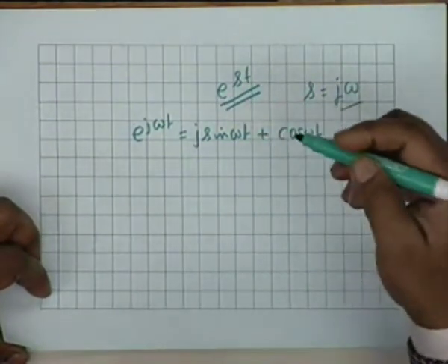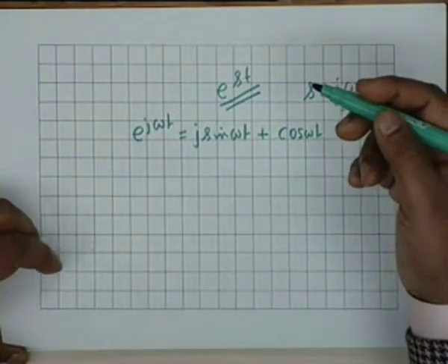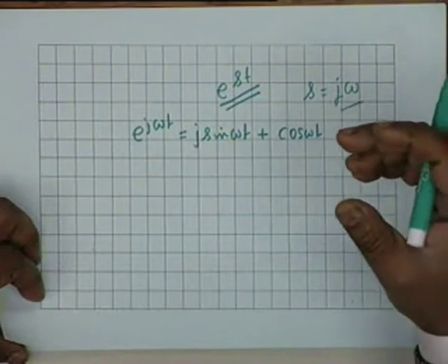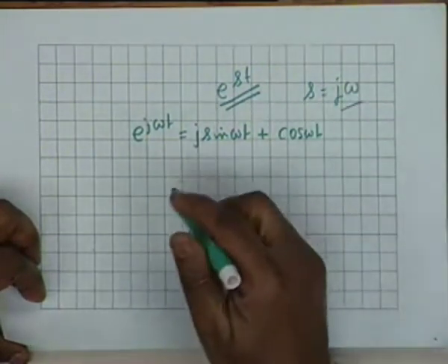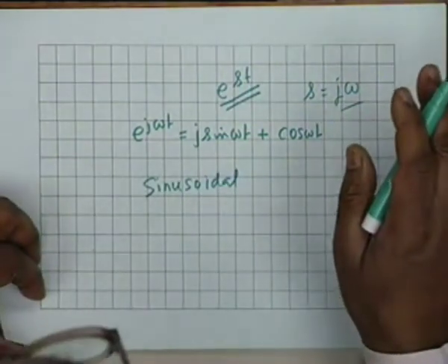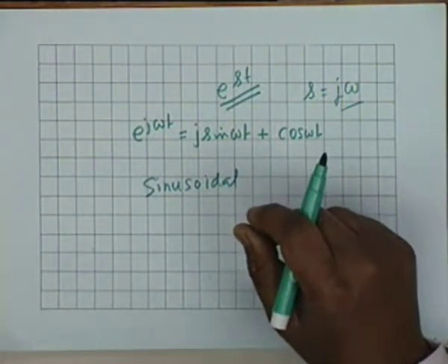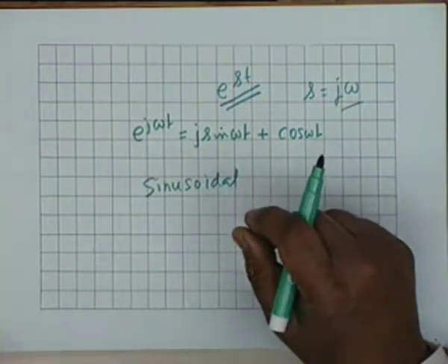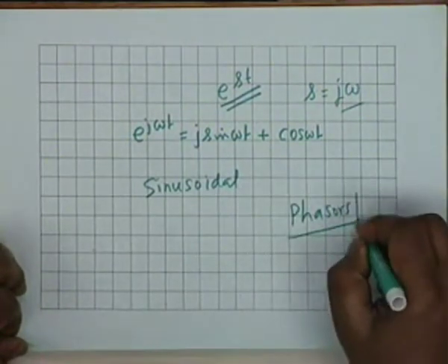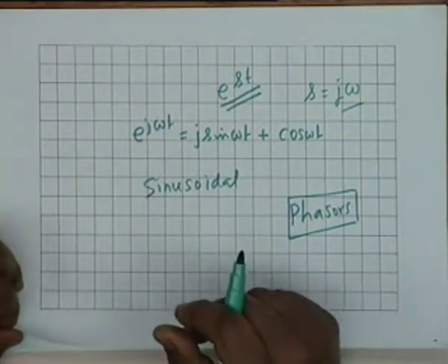Manipulating sine and cosine functions is a difficult job. It is time consuming. You have to keep track of the signs, phases and all kinds of things, and therefore what we wish to do is to get a simplified concept. Somehow for sinusoidal excitation we would like to go to the impedance concept and see how things can be handled, and this is made convenient by the concept of so-called phasors. But before we introduce phasors, let's look at this sine wave or cosine wave a little more closely.